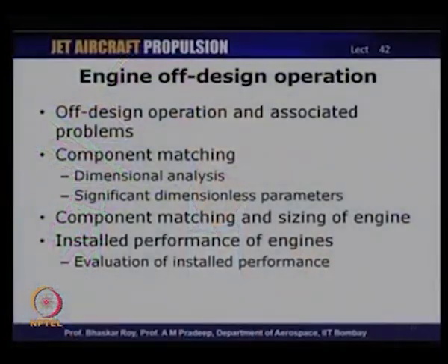And so, after we completed all the discussion on different components, we had some in-depth discussion on the engine off design operation. Though these engines are designed to operate under certain conditions, obviously we know that they have to undergo operation under all other kinds of conditions, which are referred to as off design operation. So, we have seen what the problems associated with off design operation of an engine are, and why it is important that we have a proper matching of different components. In the beginning of the lecture, I mentioned that even though these components are designed as individual units by separate teams, eventually they all have to be put in place in a single engine. They have to operate efficiently as one unit. So, component matching is a very important aspect.